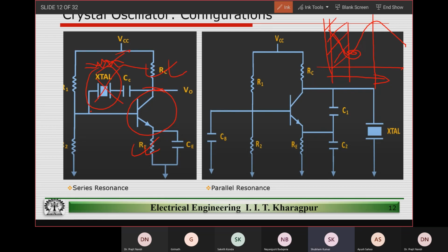One more query: the circuit on the left-hand side has current feedback, not voltage feedback. Yeah, but that is how you look at it, current or voltage, right? Why do you say there is no voltage feedback on the left-hand side? Because finally there is a capacitor, so if this node goes up, the voltage goes up, this voltage will also go up. You are thinking of it as a current because you are seeing this BJT here. Yes, sir. But I can replace that BJT with an NMOS. There will be no problem. We'll discuss this again tomorrow, Shubham, right?